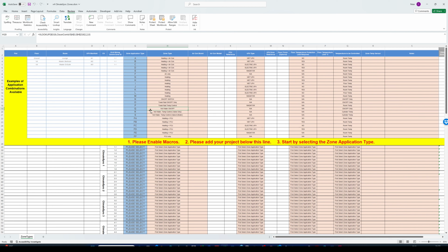Type R and S. So R is hot water with temperature control, where it will activate only the valve, but will activate it based on temperature control. So we will take a temperature sensor, and put it inside the cylinder, the hot water tank, thermal well. Put the temperature sensor inside, and we can control the water temperature in the cylinder.